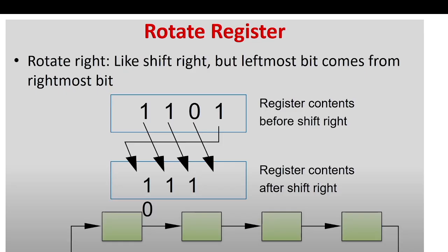Now the rotate register: if we connect this output to this input, it is like shift right, but the leftmost bit, instead of being filled with the shift-in value, is filled with the rightmost bit.